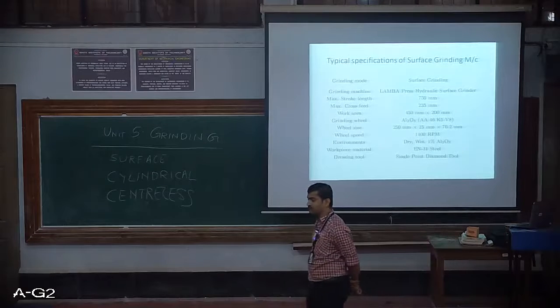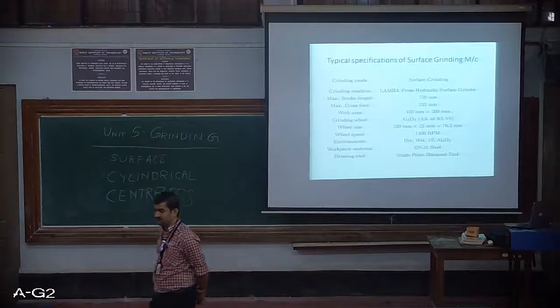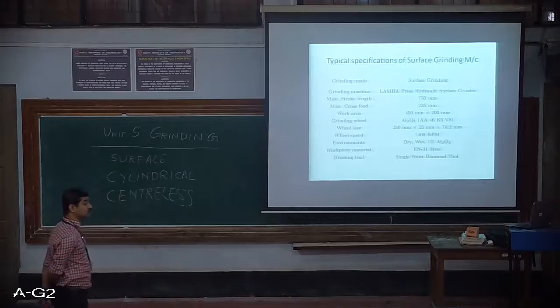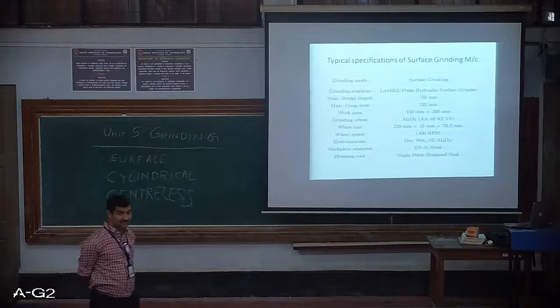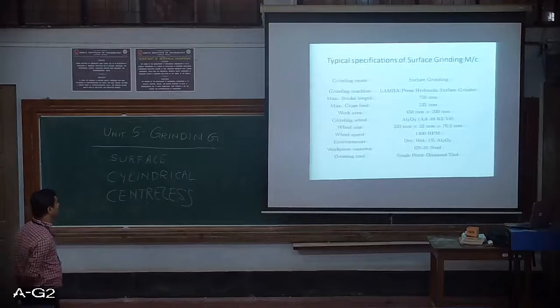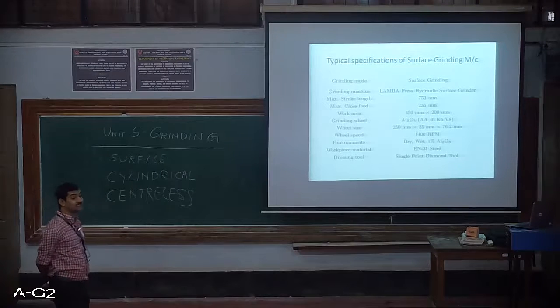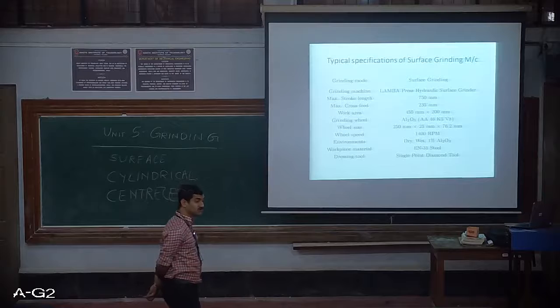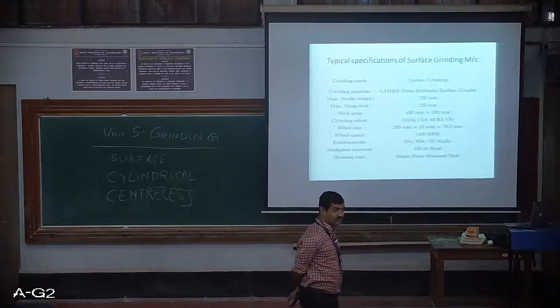Grinding wheel now comes here. The next part of the chapter deals with this. What is the type of grinding wheel? What are the abrasives? What is the bond? What is the mechanism? And so on. So nomenclature, which we call it in short. You can see the grinding wheel has an aluminum oxide abrasive, Al2O3.